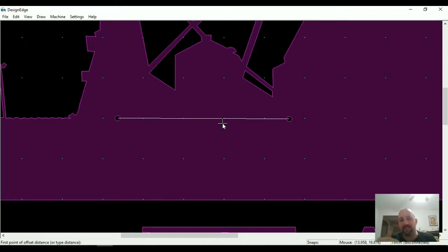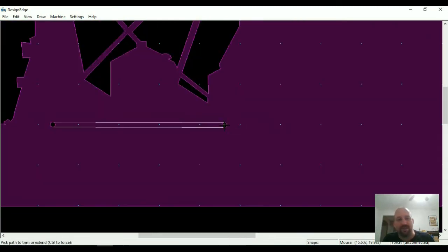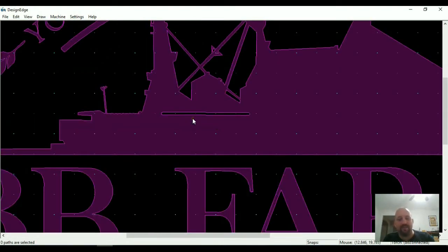But my offset is going to be half of the diameter of that circle. So 0.0625 for a 1/16. I'm going to hold Control, and that's going to jump and copy one direction. I'm going to let go of Control and click on the other side, and that'll actually move that one. And then I can X trim those out and hit J. And that line will give me some definition on that Quonset Hut. Looks to me like there's a little window.